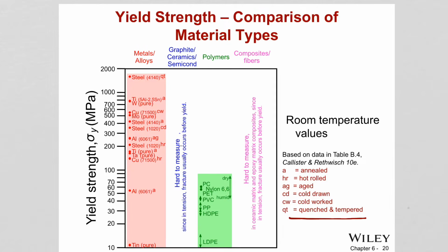So later we're gonna learn these heat treatments, because sometimes materials, to enhance their properties, have to go through certain heat treatments, meaning we increase the temperature, then suddenly quench, meaning suddenly drop into water. And this causes, for example, small grains in steel. Therefore, the strength of the material is increasing, for example. Or different types of heat treatments can be given depending on these ladders we are seeing.